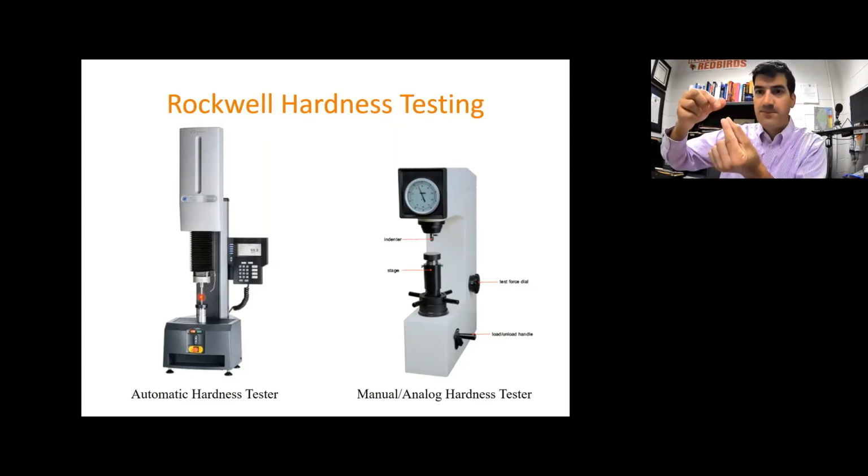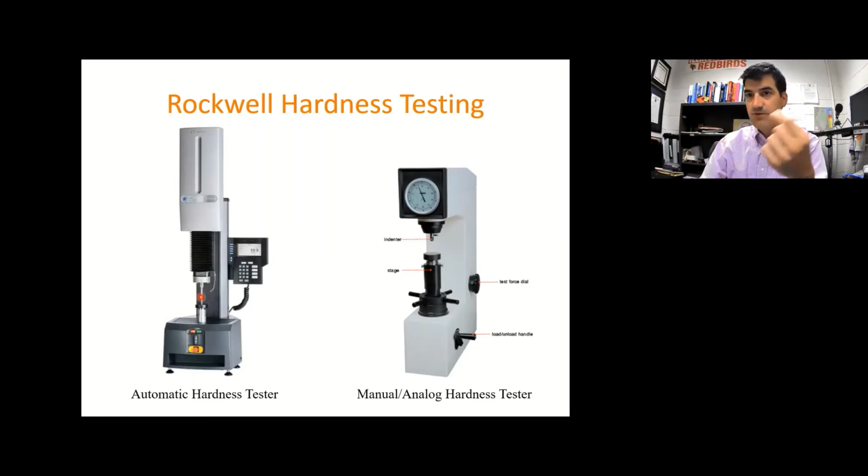There's a little thumb screw that you just loosen with your fingers, and then you can take the old indenter out, whatever it is, and then you slide the new indenter up in there, and then you tighten up the thumb screw. It's kind of like putting a drill bit in a drill press, if you've ever done that before. So it's not hard.